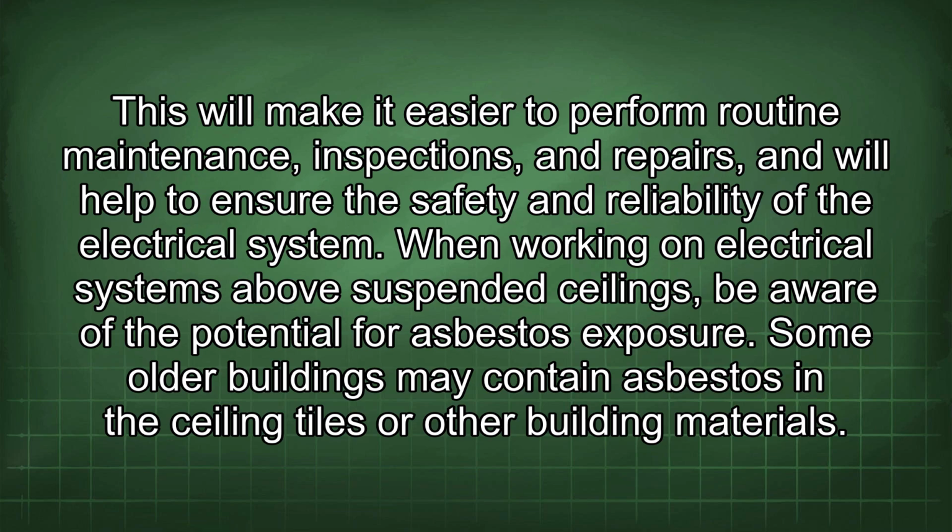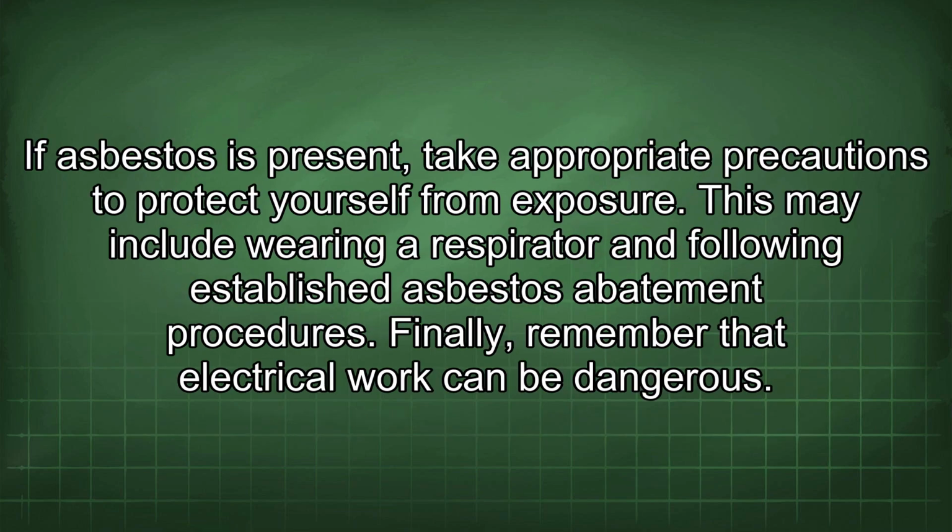When working on electrical systems above suspended ceilings, be aware of the potential for asbestos exposure. Some older buildings may contain asbestos in the ceiling tiles or other building materials. If asbestos is present, take appropriate precautions to protect yourself from exposure. This may include wearing a respirator and following established asbestos abatement procedures.